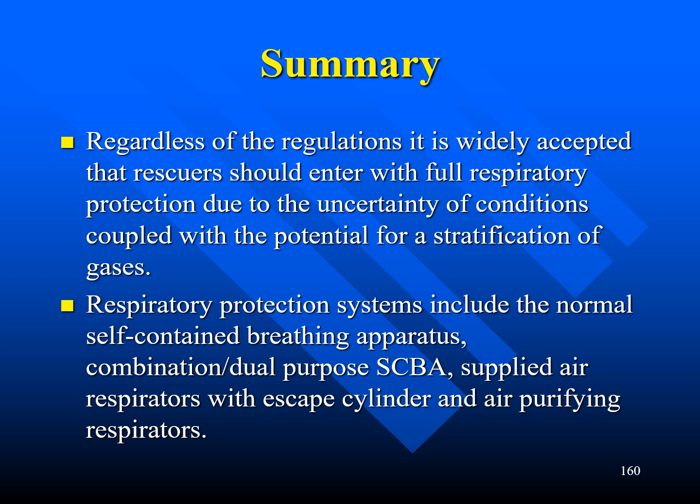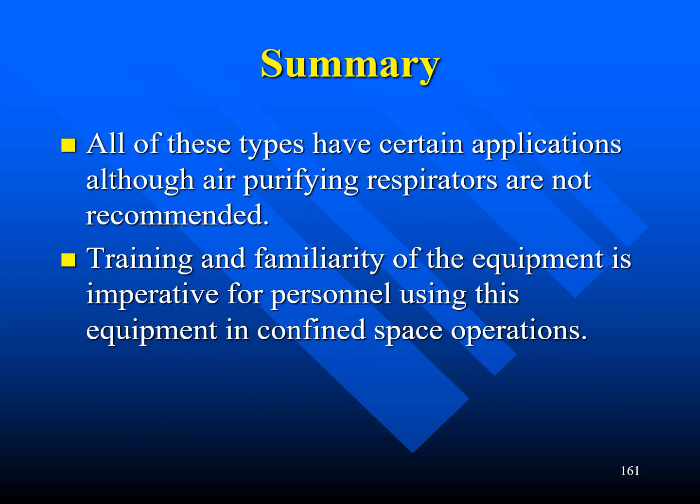Respiratory protection systems include the normal self-contained breathing apparatus, a combination dual-purpose SCBA, supplied air respirators with an escape cylinder, and air purifying respirators. All of these types have certain applications, although air purifying respirators are not recommended. Training and familiarity with the equipment is imperative for personnel using this equipment in confined space operations.